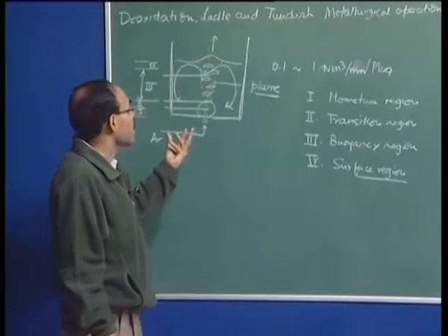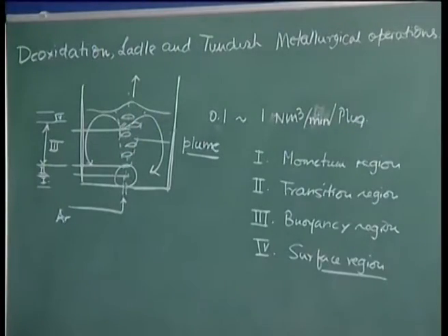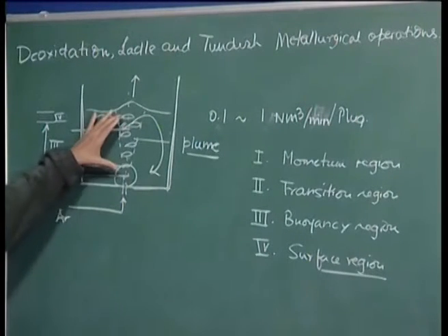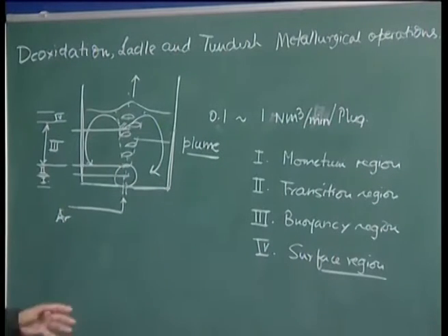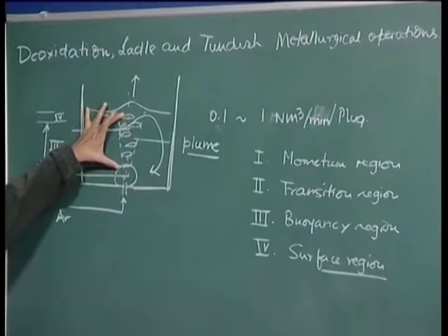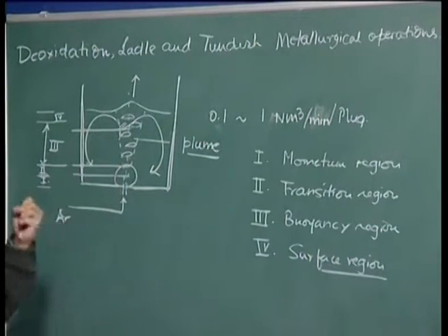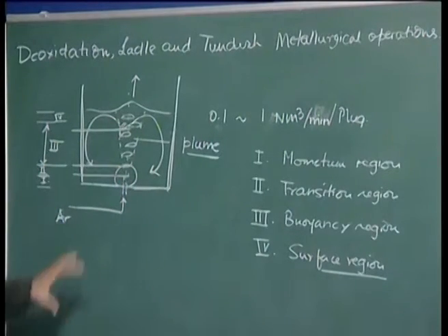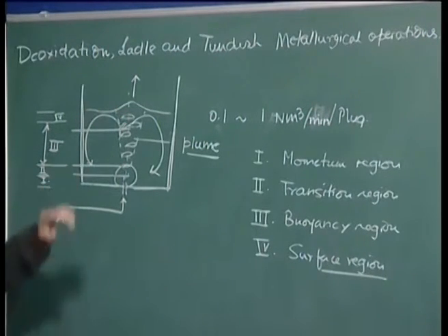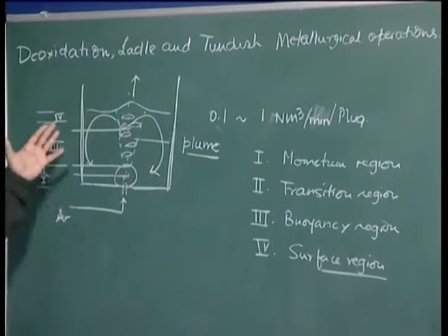Tiny, very small spherical cap bubbles or ellipsoidal bubbles are not possible there, because we have standard charts or nomograms available, which give us the shape of bubbles which are possible in various liquid systems in terms of Eotvos number, Reynolds number, and so on. So, these spherical cap bubbles which we see within the core of the liquid, and their equilibrium size, are more or less governed by the thermophysical properties. We of course have a spectra of bubbles. There is coalescence and disintegration of the bubbles, and a dynamic size range develops within this system, and the mean size range here is governed basically by the thermophysical properties of the gas-liquid system.